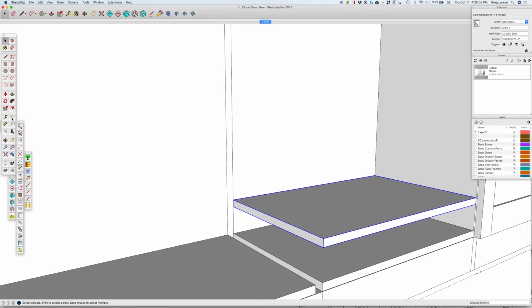All right, so we use the rotate command. Here we go. You see how this switches around? Depending on what face you're on, it changes color to that axis. But I want to stay on the green axis, so what I do is make sure it stays green, nestle it down in that corner until I get the green.